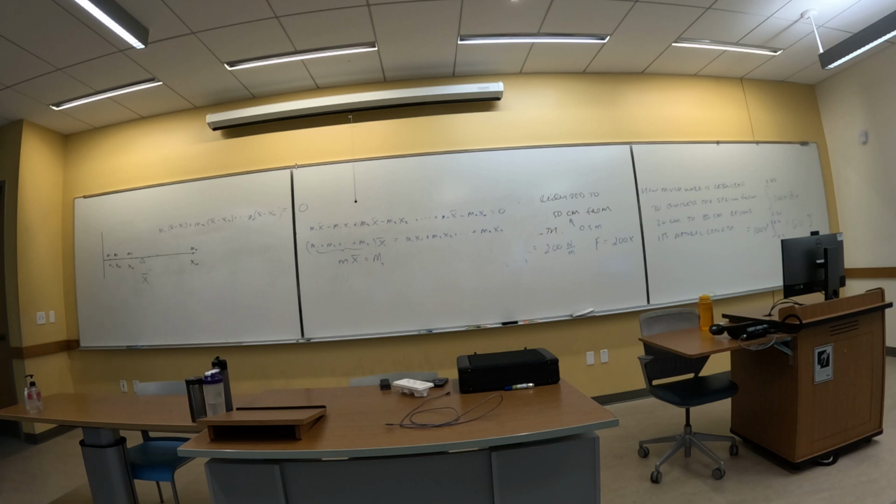Right now, this seems like a 1-dimensional problem. It is. So I'm measuring all my distances where? To the y-axis. I'm not really truly in 2 dimensions yet. I'm 1-dimensional, but all my distances are measured to the y-axis. So that's why we call it M subscript y. Okay?